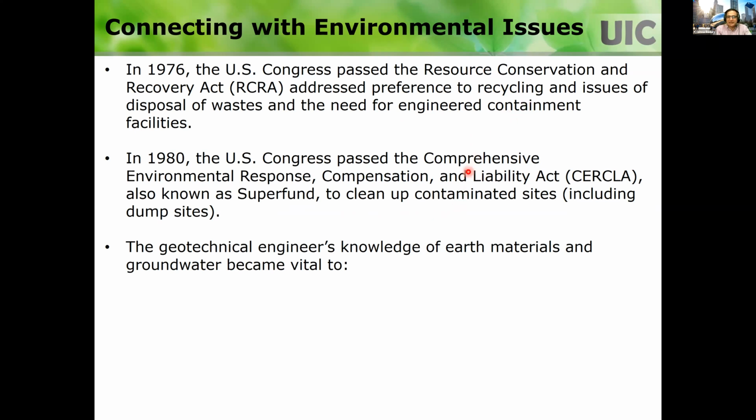Engineered containment is like a landfill, that deals with the soils. Recycling, basically, is substituting the soils with these waste materials, and cleaning up contaminated sites involves soils and groundwater. So, geotechnical engineers have the background on earth materials and groundwater, so they started to play an important role in characterizing and reuse of waste materials.